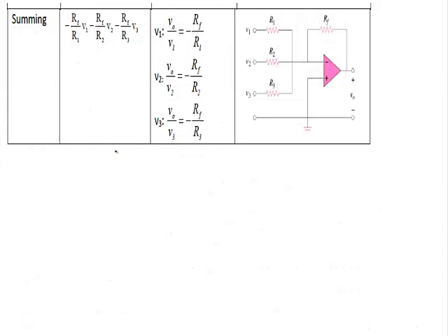The last type of op-amp we'll look at today is a summing amplifier, or an inverting summing amplifier. Why is it called inverting summing? Because what you'll notice here is that all of the voltage inputs are tied to the negative terminal and all of the gains are negative. We won't actually do KCL in order to find the output for this one, but we will do superposition.